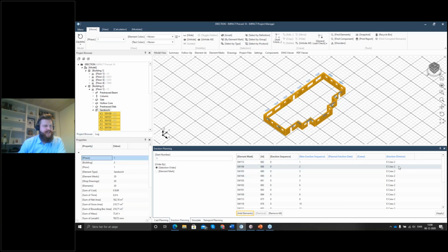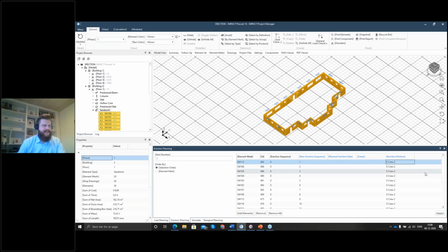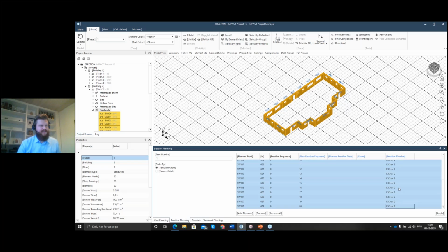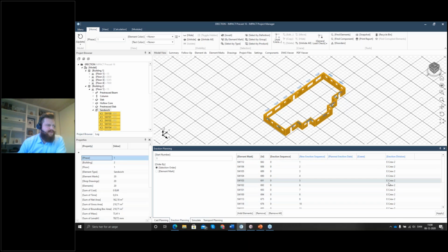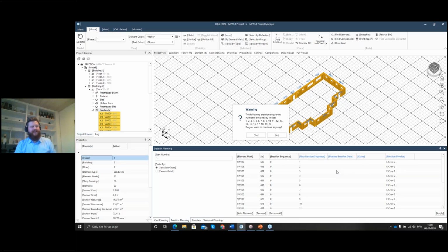And in this case, usually this one would be empty. And this is simply because, of course, I did a small test before we went into the live webinar. But other than that, simply you select the erection division here. So we have erection crew 2. We're starting the erection sequence at number 1. We're clicking apply. Now it says the following erection sequence is already in use. Are you sure you know what you're doing? And I am, because I want to erect these at the same time. So I'll just click yes.